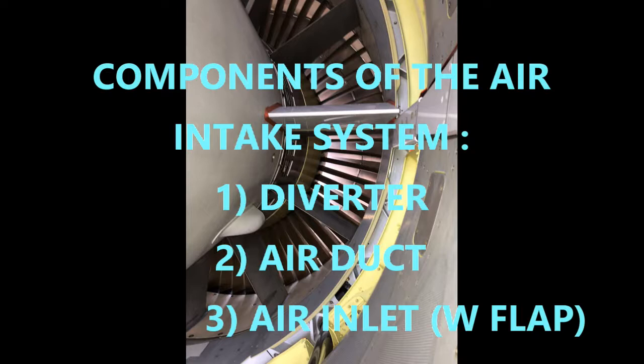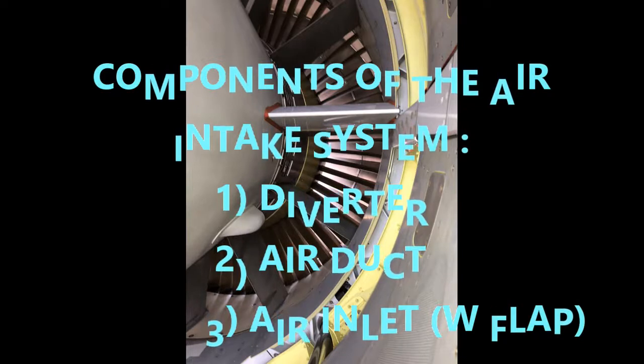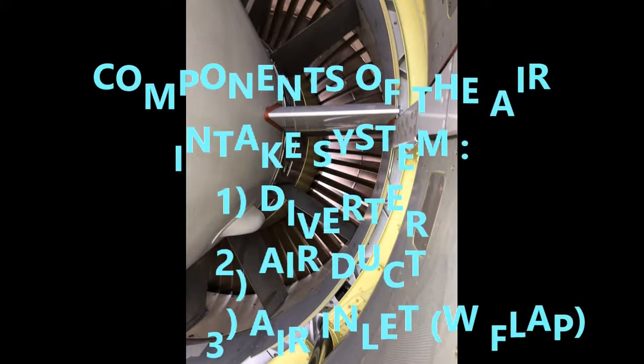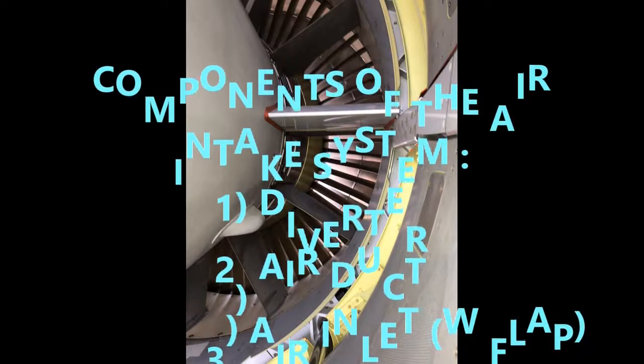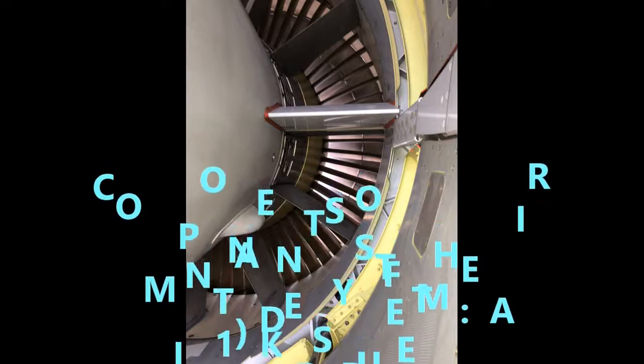Okay, your air duct actually has two major components, joined by brackets and fasteners. You've got an elbow as well. The purpose of the elbow is to redirect the airstream into the plenum chamber of the APU. Then you have the diffuser. What that's doing is decelerating the airspeed. It's diffusing, so it's causing a slowing down of that air. It's working together in conjunction with everything else.